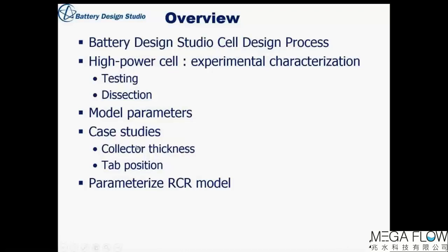We'll look at the effect of current collector thickness on the cell behavior and also the tab position. And then finally, we'll use the physics model to parameterize an empirical circuit model, the RCR model, and then hand that model off to Gaetan to use in the pack simulation.